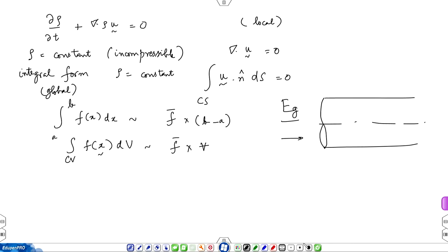Now, I will not repeat it, but it should be second nature to you, but you have done this earlier. You set up a free body diagram. So, here what do you do? Set up a control volume. Okay. Set up the control volume for analysis. So, this control volume will contain the fluid medium, it will not contain the tube. So, control volume is inside the tube.